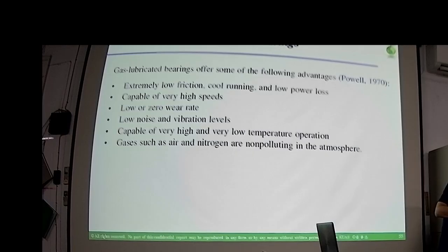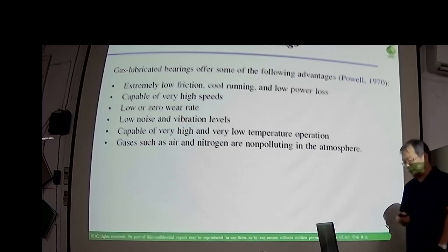some advantages for the air bearing. So you have extremely low friction, it's full running and low power loss. Capable of running a very high speed, low or nearly zero wear rate, and low noise and vibration level.